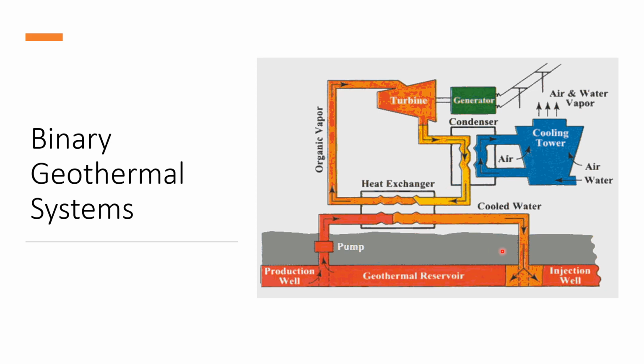Another diagram for your binary. So production will go up. Heat exchanger is the key point for your binary geothermal system. Now there's your secondary liquids here, exchanging, and then we've got your organic vapor. Heat exchange gets a lower temperature state. Turn the turbine. Turbine is going to run the generator, and then you're going to get your electricity.